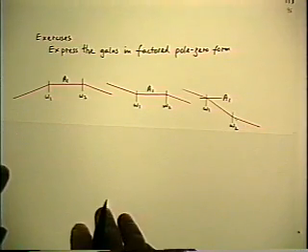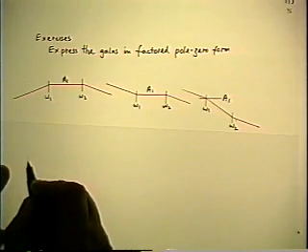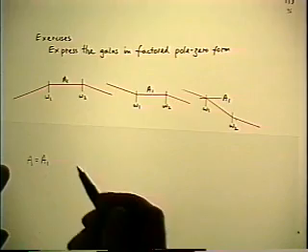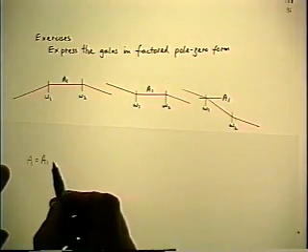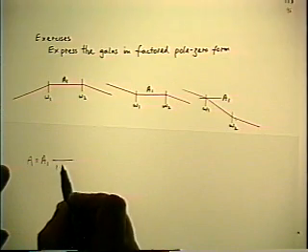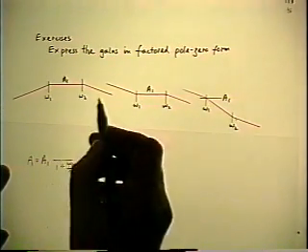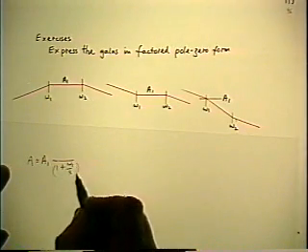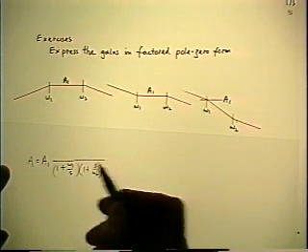Let's look at the first one. One flat gain. Take that as reference, A equals A1, look up and down in frequency. If you look down in frequency, there's a concave downwards corner, so that's an inverted pole at omega 1. Look up in frequency, concave downwards corner, that's a normal pole, 1 plus S over omega 2, no zeros.